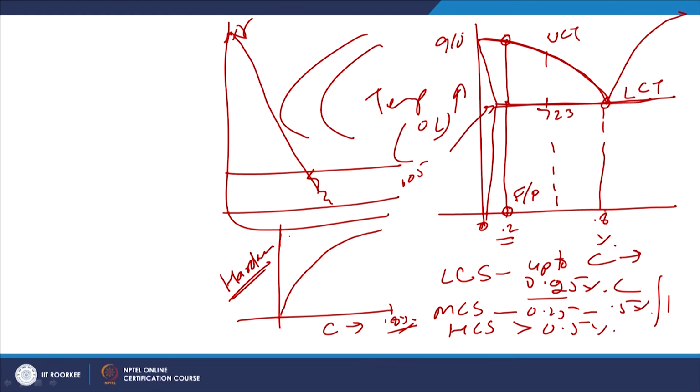So, this shows an increase in hardness from 20 HRC to 60 HRC. There will be a continuous increase in hardness. So, it is not guaranteed that 0.3% carbon steel, when subjected to the austenite to martensitic transformation, will get too high a hardness; the hardness will be limited.